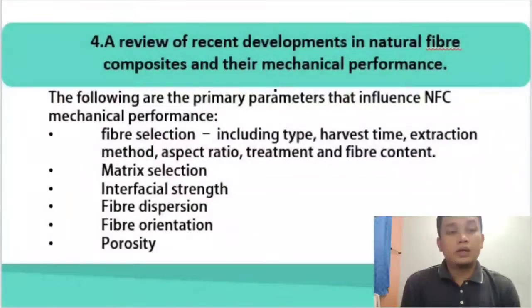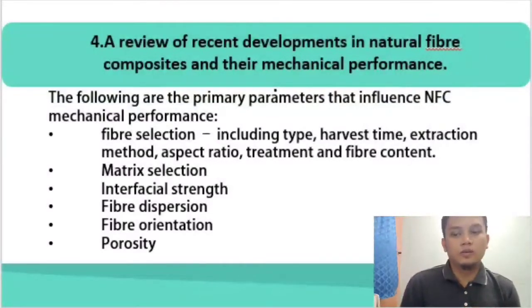Following are the primary parameters that influence NFC mechanical performance. The first one is fiber selection. In fiber selection, it must include the type, harvesting time, extraction method, aspect ratio, treatment, and fiber content. The next parameters are matrix selection, interfacial strength, fiber dispersion, fiber orientation, and also porosity.